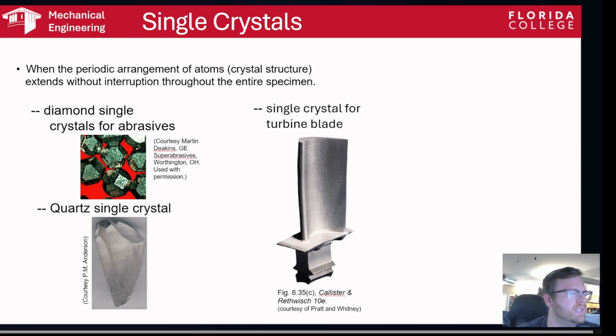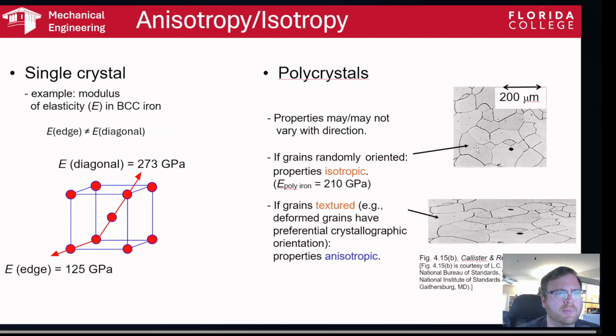Whereas I would say most of the time engineers prefer to work with isotropic materials like aluminum, usually standardized aluminum and steel. They tend to be isotropic materials. And we prefer isotropic materials because we don't have to run constant tests on our material to figure out which way we're looking. I don't know if that makes sense. You can't tell easily which way your crystal structure is directed. You have to use a scanning electron microscope or something, and it's a lot of work.